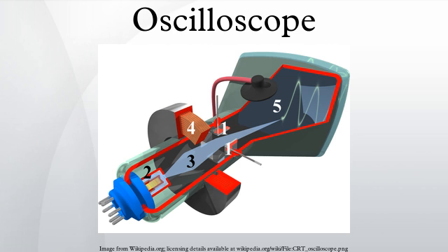Horizontal position control. The horizontal position control moves the display sidewise. It usually sets the left end of the trace at the left edge of the graticule, but it can displace the whole trace when desired. This control also moves the XY mode traces sidewise in some instruments, and can compensate for a limited DC component as for vertical position. Dual trace controls.